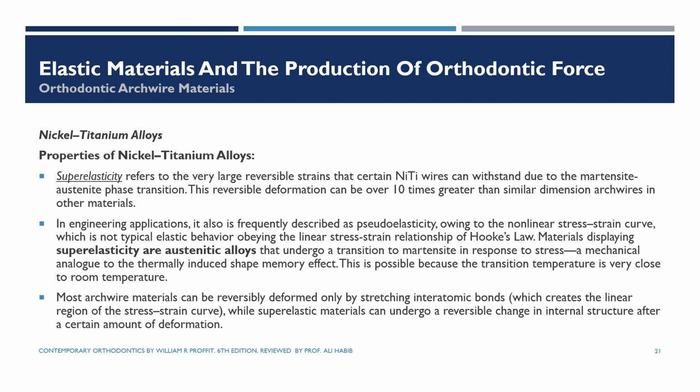A feature of the nickel titanium alloys, besides the shape memory and the heat activation, is superelasticity, which refers to large reversible strains that certain types of NiTi wires can withstand due to the martensite-austenite phase transition. This reversible deformation can be over 10 times greater than similar dimension arch wires in other materials. So superelasticity means that when the wire undergoes stress, it transforms from one phase to another, not due to temperature change, but due to stress application.